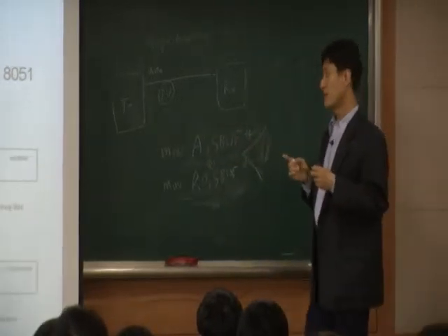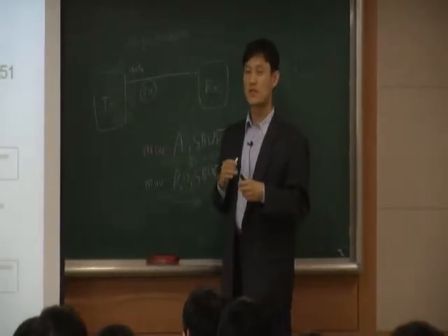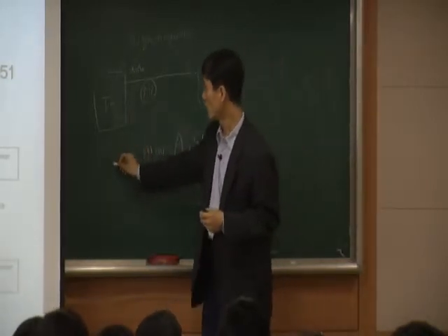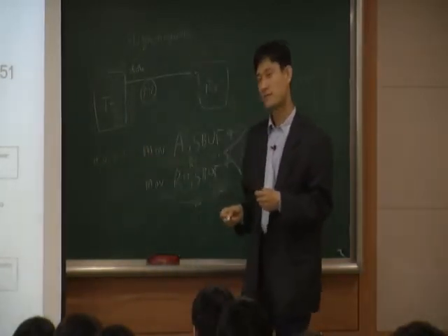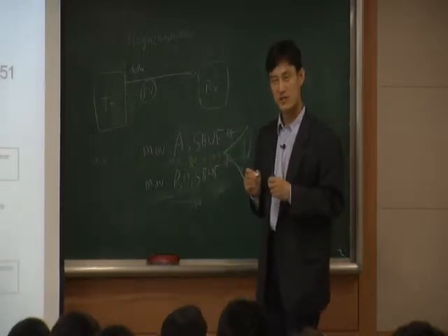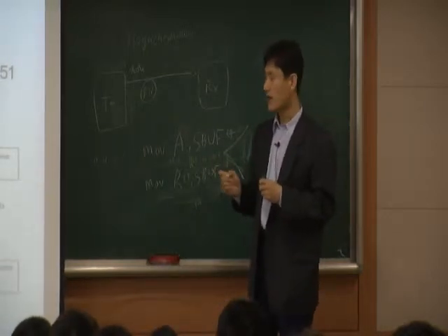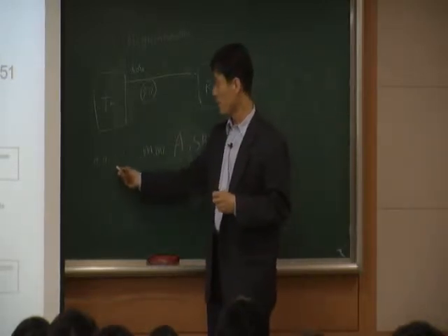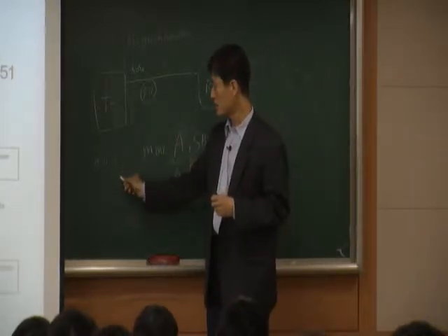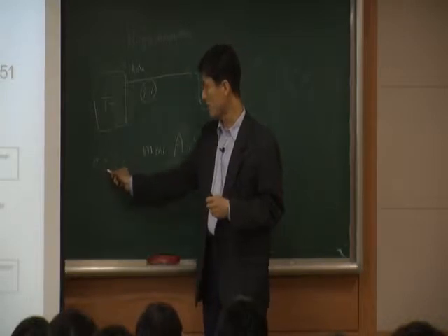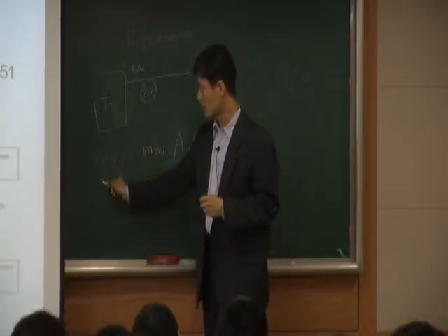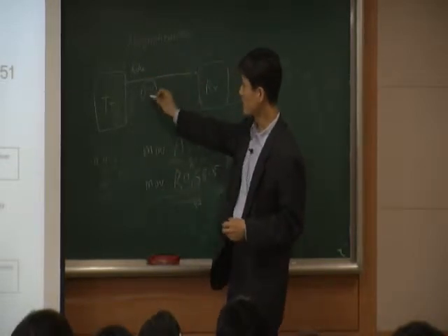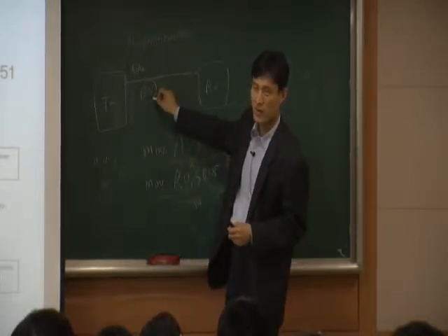Now suddenly, the transmitter wants to transmit some value. Let's say I want to transmit 1100. Suddenly, I want to transmit. How can you do it? Maybe 1 corresponds to 5 volts, and 0 maybe is 0 volts. In that case, we have a problem, because this wire is already 5 volts when you do nothing.